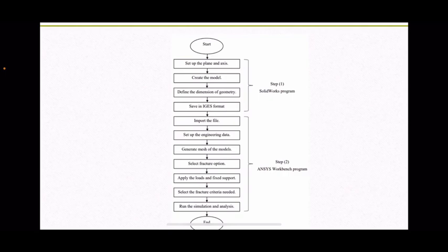Then select the fracture criteria needed, like the stress intensity factor and the minimum strain energy density. Then finally we run the analysis. Then we get the data and create the results and the discussion from it.